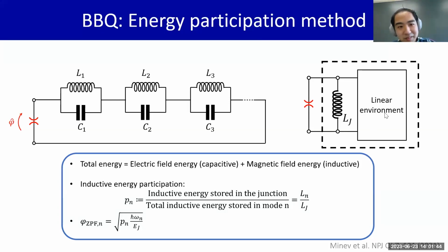So it's possible to extract that ratio from HFSS as well, because for each eigenmode there's always a conservation law, an equal partition of energy: the inductive energy and the capacitive energy should equal each other. Or put it this way, the energy stored in the E field and the energy stored in the B field, the magnetic field, is always equal to each other.